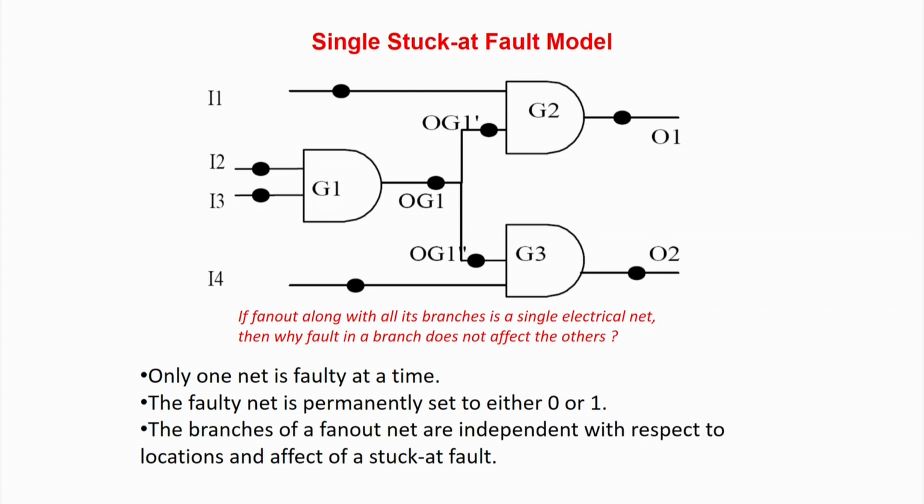Again, we discussed that the single stuck-at fault model is one of the most widely accepted fault models, because until 10 years back, if you could verify that there is no single stuck-at fault, the circuit could be considered to have no faults, and the correlation was also very high. So what was the stuck-at fault model? You assume that each of the lines of a circuit can be either stuck-at 0 or stuck-at 1, and you have to verify, by test pattern application, that none of them occurs. Generally you call it the single stuck-at fault model because you consider only one line at a time. That was one of the most de facto applied fault models, the first fault model on which almost every circuit test was based.